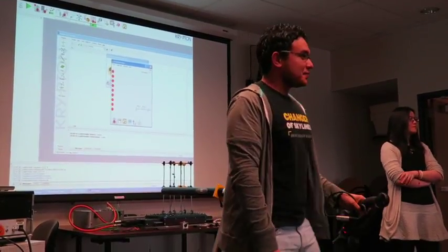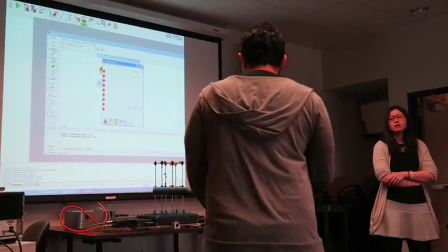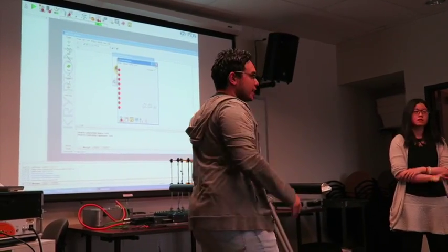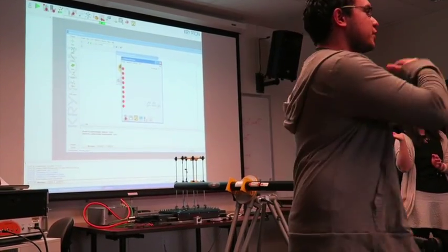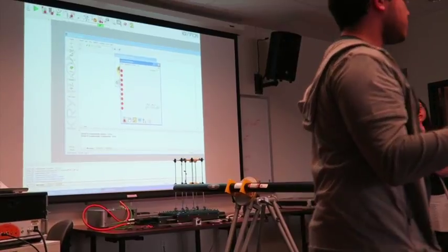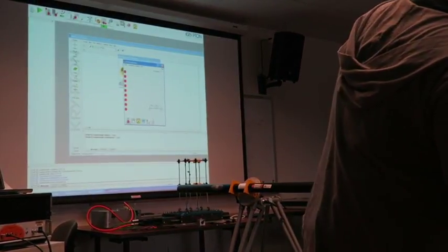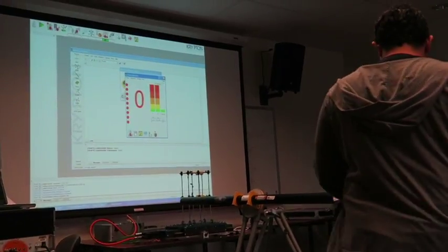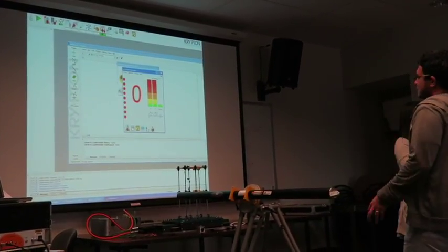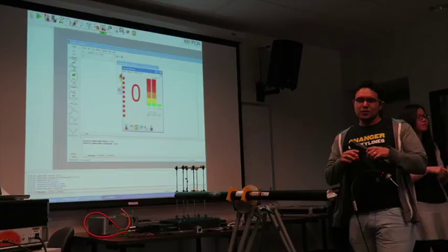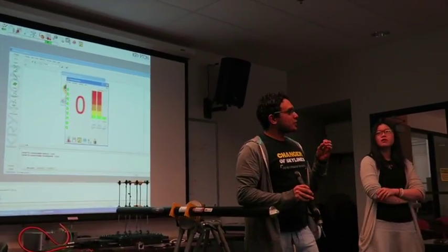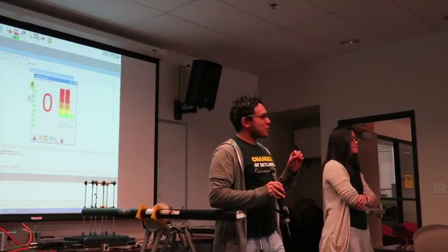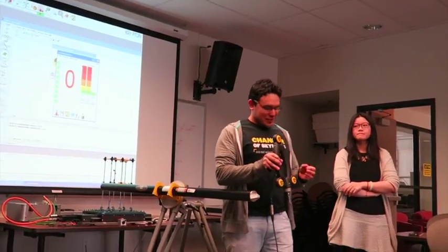So how many points do you need to capture? You need to just put those bars in the green area. Basically, you need to cover some angles: back, forth, left, right, each direction 5 points at least, and then it's suggested. This is a trade-off between how many points you want and making sure you don't move your probe. For that reason, you don't want to recalibrate every time. You just want to reuse it. You want to calibrate the first time and that's it.